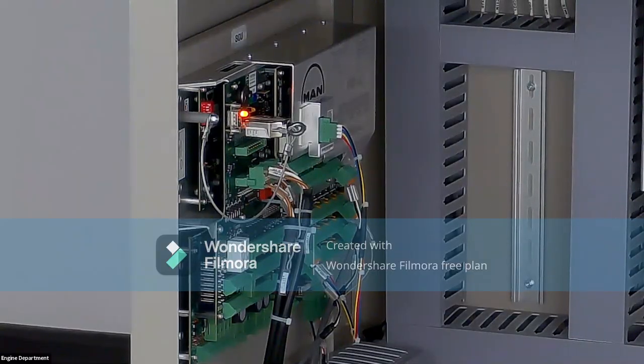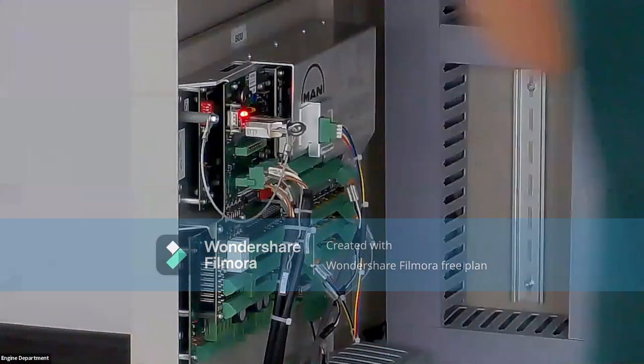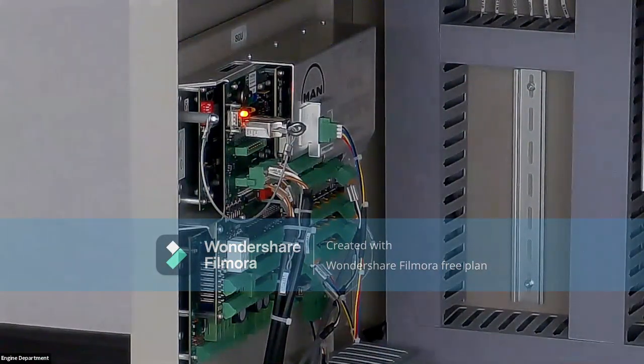Okay, let's see, 2 red, 3 green. So gentlemen, if you notice, now the LED changed the flashing mode to 2 red, 3 green. Okay, this means that the installation has taken place, and for normal operation of the respective MPC it is required to change the DIP switch number 4 to on.